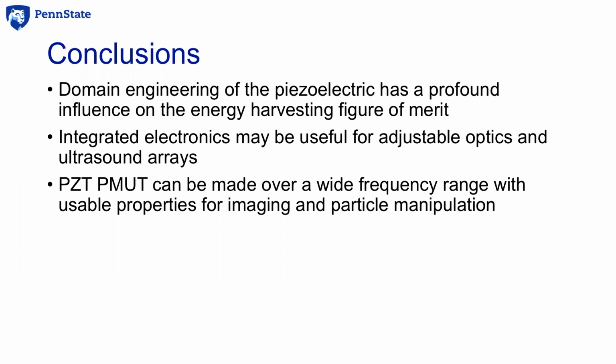That's a beautiful question. So practically, we've been working on lead zirconate titanate films and how to optimize the properties of those films for almost 25 years. And so some of my new students don't have to come in and reinvent that base technology, which is why they're able to move forward to make devices. When we are starting brand new device fabrication, the first thing we try and figure out is literally what order of the steps we are going to do. And it normally takes a student at least 6 months to learn how to do all the steps. And not uncommonly, the first device run of any device might take several months to complete.